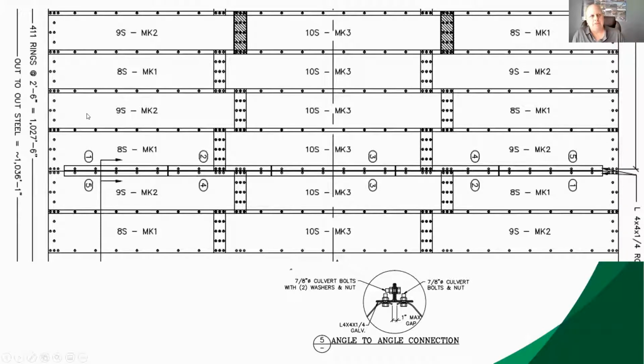One of the neat things about flexible buried bridges is that theoretically each ring, when assembled and properly backfilled, can carry the design load. So there is no function of this joint between rings other than basically holding the plates together and making a continuous structure. So there's no design load that's considered in these locations, and that's why these flange connections work here.